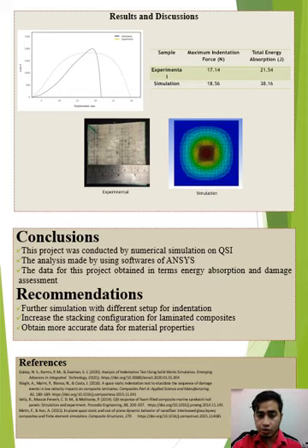The FE model was modeled as a single plate rather than the original model, which is a 5 mm strip unidirectional mat in the design modular. The original model was too complex and takes a lot of time to compute results. Therefore, the model was simplified into a single plate and defined as 4-ply layer mats with different orientation order to save computational time.